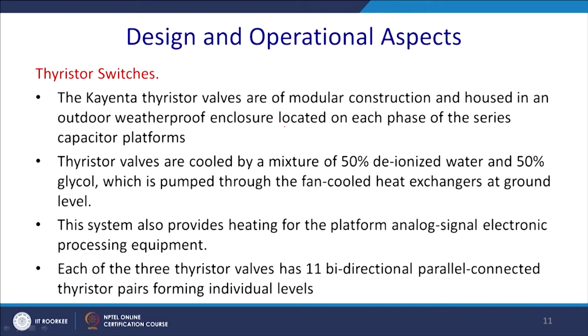Thyristor valves are cooled by a mixture of deionized water and 50% glycol, which is pumped through a fan cooled, that means actually force air cooled, heat exchanger at ground level. The system also provides heating for the platform of the analog signal electronic processing equipment. So, it will also maintain the ambient temperature for those components.